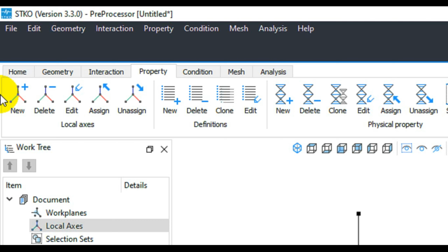And for consistency and continuity, the orientation of the local axes across the elements in the model is critical for ensuring continuity and avoiding discontinuities in the analysis. So that's very important. Sometimes we face some challenges in aligning the local axis definition. One is automatic assignment. Some software provide automatic assignments, which is challenging and prone to potential misalignment, affecting accuracy in the simulation. And manual adjusting is also challenging.